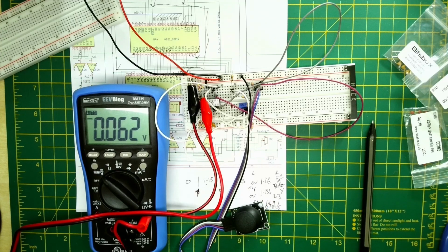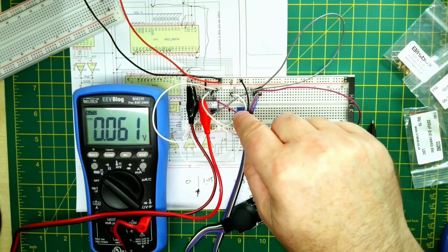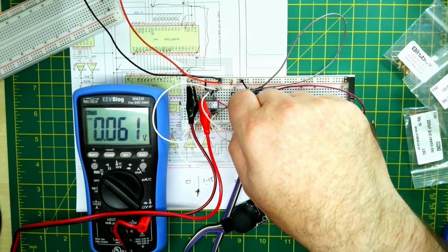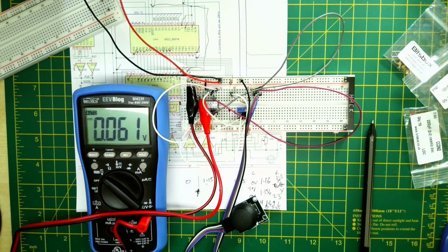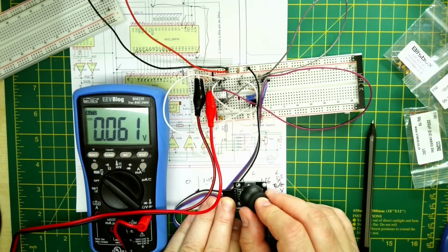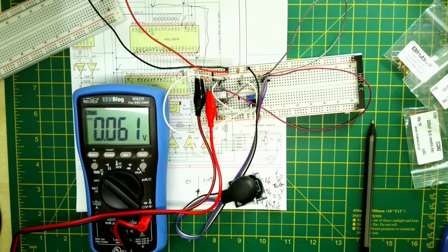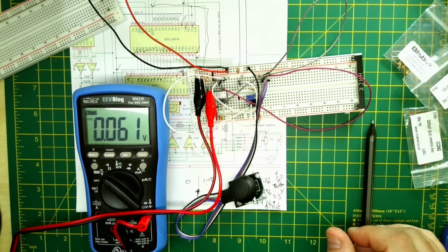Okay, so it took a little while to work out this circuit, and what I have here is a little trimmer potentiometer, a 10-turn one, so we can actually vary the range. If we were playing games and found it a bit too sensitive or not sensitive enough, then we can narrow the range over where the switch kicks in.